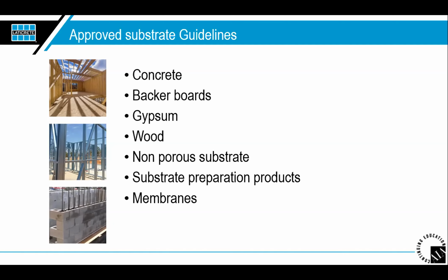Substrate preparation products: self-leveling underlayments, patch and primers. That's something that the installation material companies are going to provide for you. We used to have to use lath under every self-leveling product. That's not the case anymore. We've got away from that. We do have minimum thicknesses there, but it can be achieved, and we can go directly over wood installation that way, again, as long as the wood installation is meeting deflection ratings.